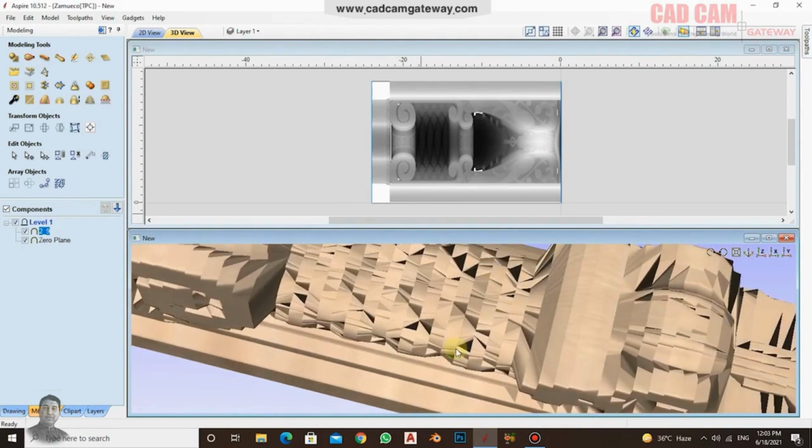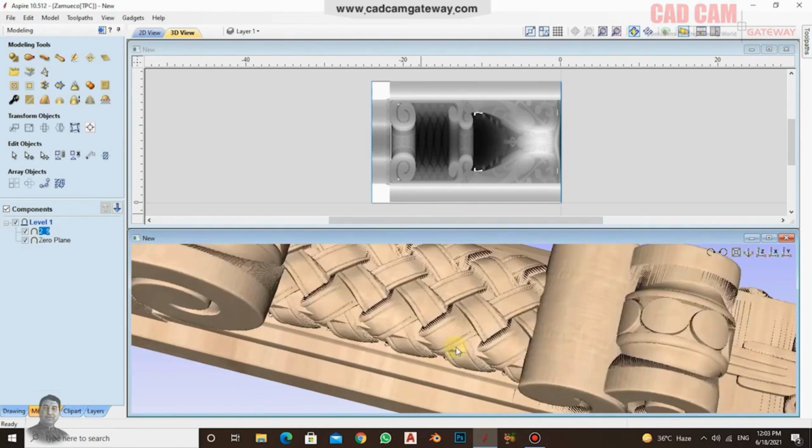Like, I recommend using up to 1.5 millimeters. Sometimes we even have to use a ball nose up to 1.75 millimeters. So, go ahead and do that if needed. But also make sure to charge the customer accordingly for this level of work. If they're paying for it, you must deliver quality work. Your machine will keep running, no problem. When the customer pays you, make sure to offer this to those customers who are quality conscious.